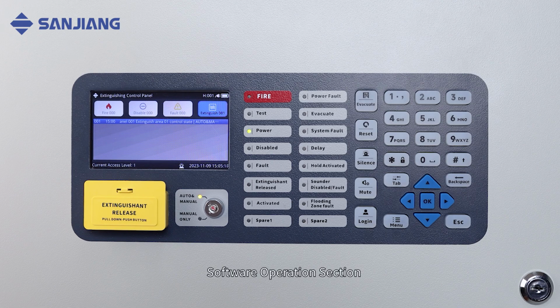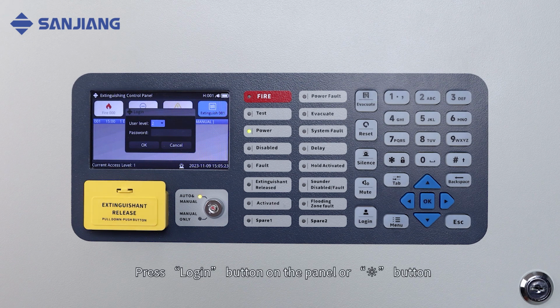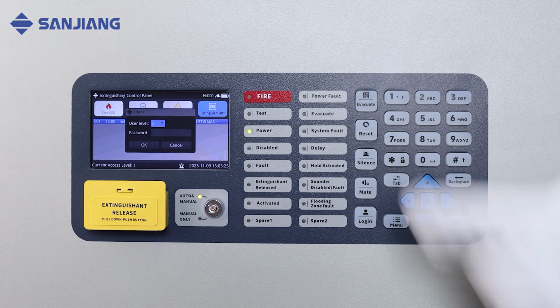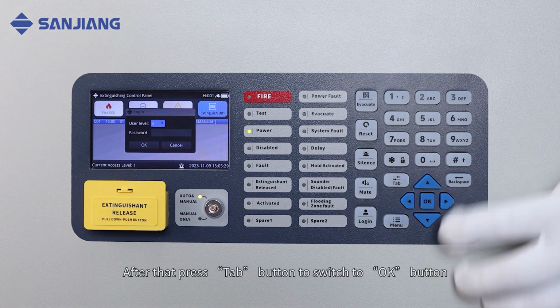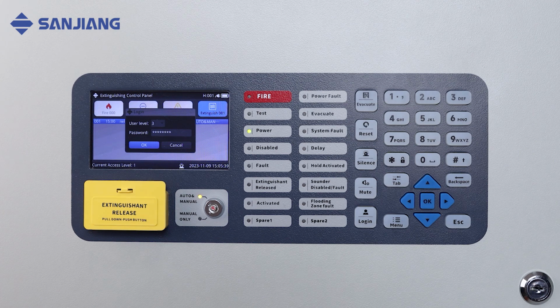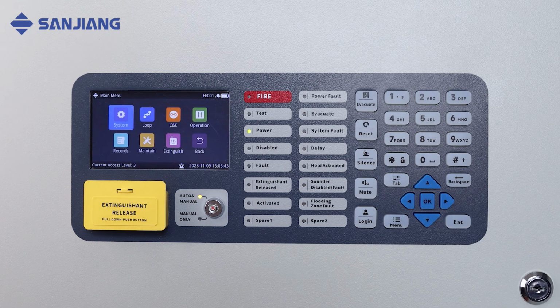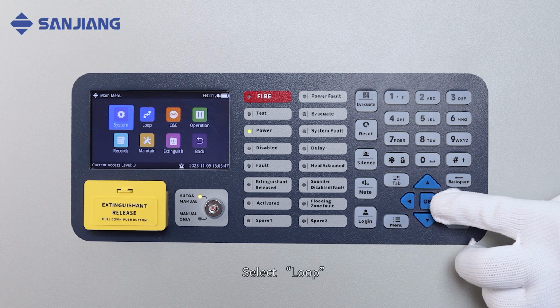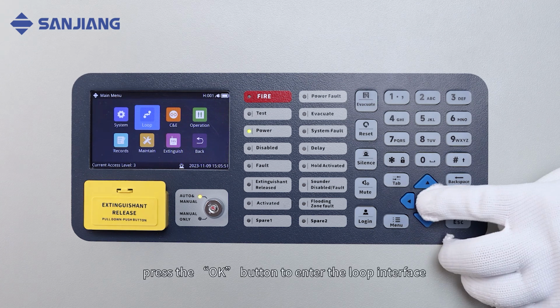Software operation section. Page login. Press login button on the panel or asterisk button. Then enter the password. After that, press Tab button to switch to OK button. Press OK button to log in. Select the loop. Press the OK button to enter the loop interface.